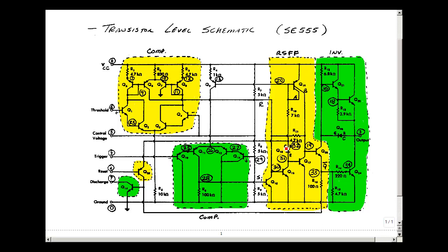Notice here that the diode that's created here is actually a shorted base collector of a transistor to make a PN junction from a transistor. It's a trick we use in IC design. You can see how I numbered all the nodes here, and I'm going to use this for the simulation.